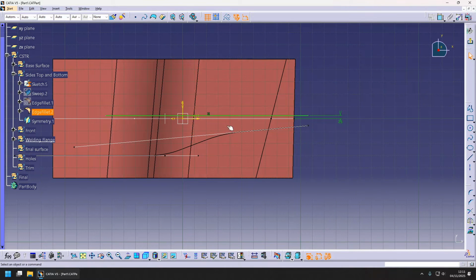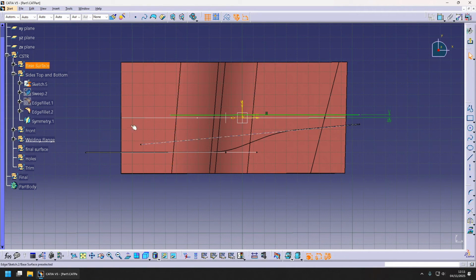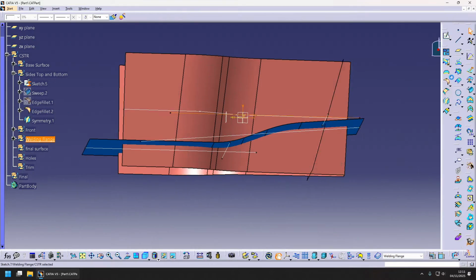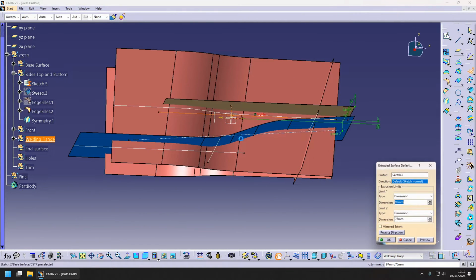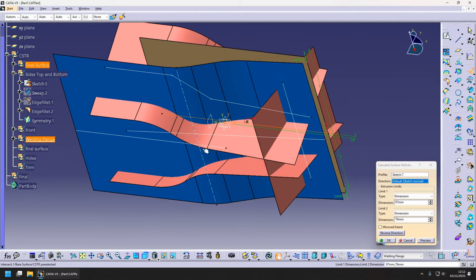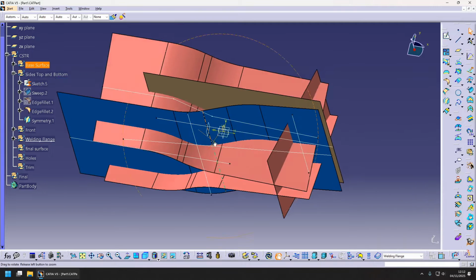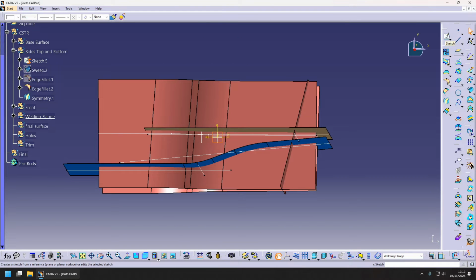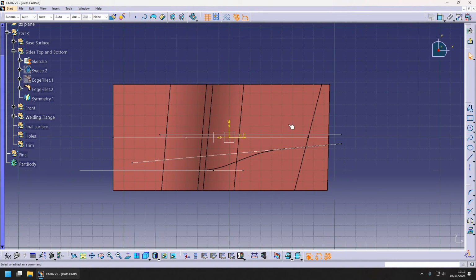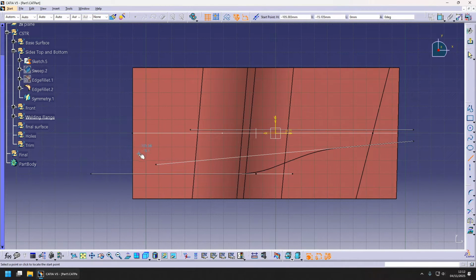Now we have the option to either continue in the sketch with all the drawing, or we can have separate sketches with separate lines. It's usually better to have them separate, but it's faster to have them in the same sketch. So really it's about defining your own algorithm of how you want to do things.